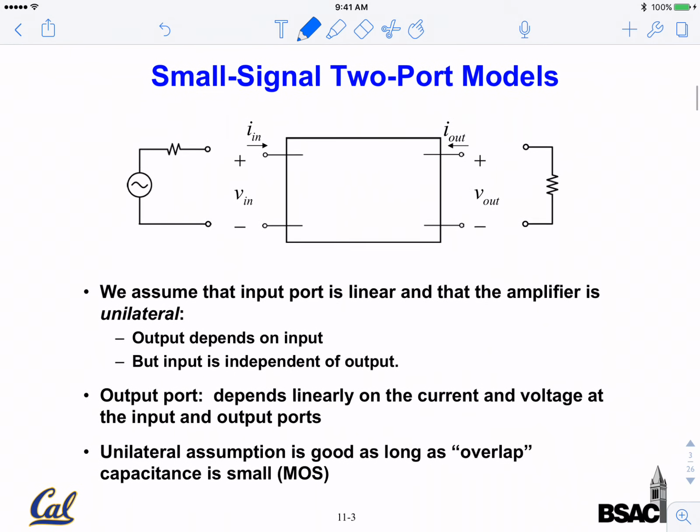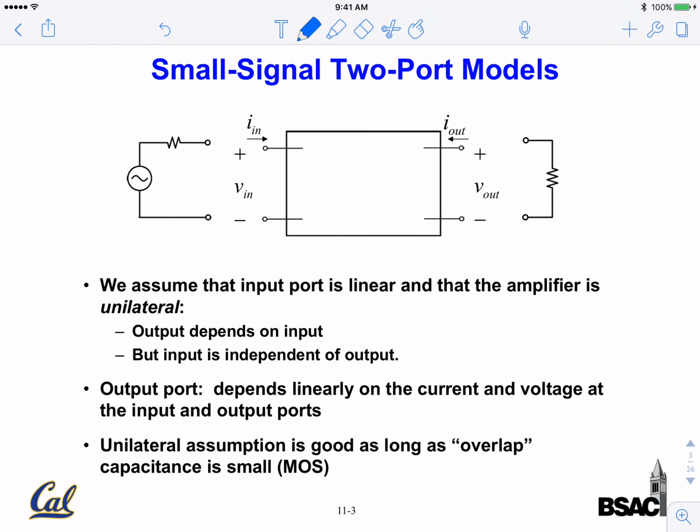Okay, so an amplifier, in its minimum configuration, is a two-port circuit. For example, this is a two-port circuit here. Again, these are high-level abstractions. Inside this box, there could be one transistor plus biasing circuits, like what we will discuss today. It can be a more complex block of circuits, with an op-amp or multiple op-amps inside.